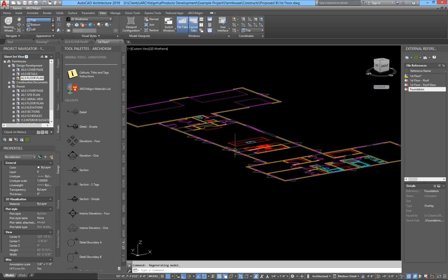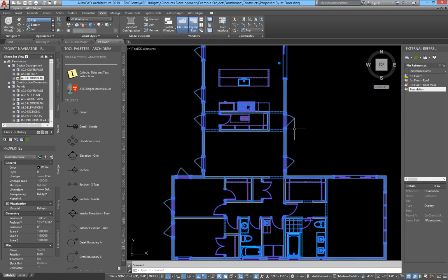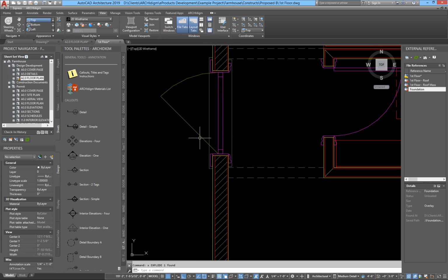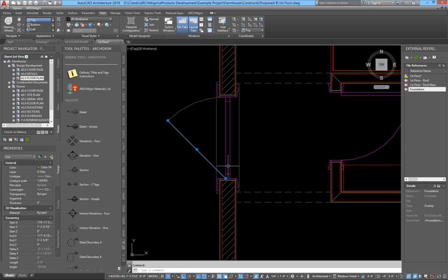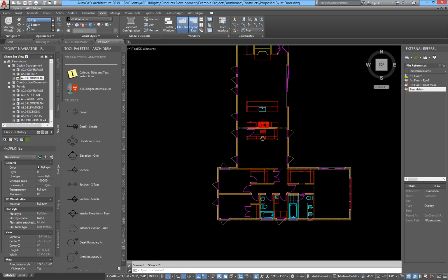And when we explode the block and go back to plan, you may not like the results. You can see it becomes an anonymous block, and I go ahead and explode it, and then I maybe pick on an object like this. So this all becomes tiny little pieces of linework. But it is successful at doing what it's designed to do, which is just create a flattened version.